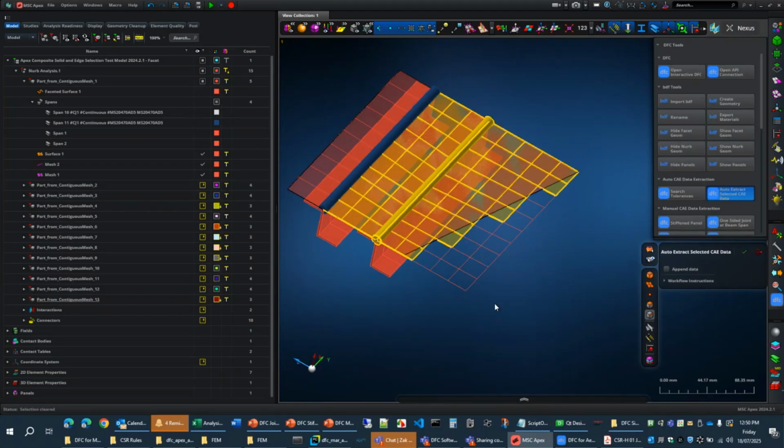Sorry, one question from my side. Up till limit load, this analysis is good because there's no plastic deformation. But if you go to ultimate loads, the fasteners can yield and redistribute. Do you have a post-buckling analysis for that or not?